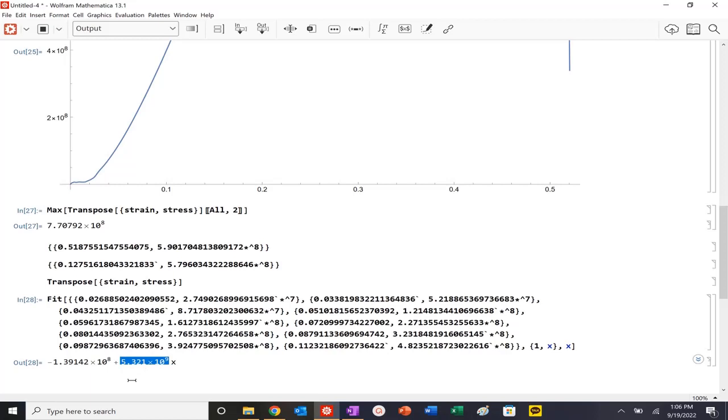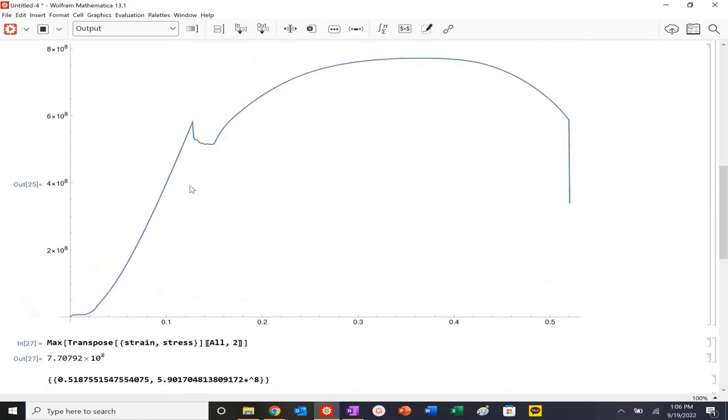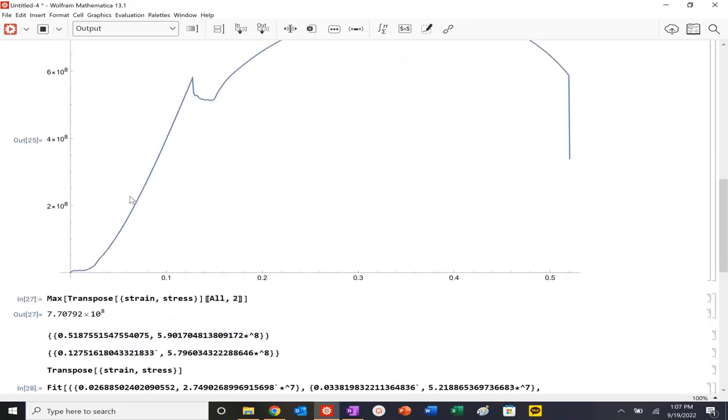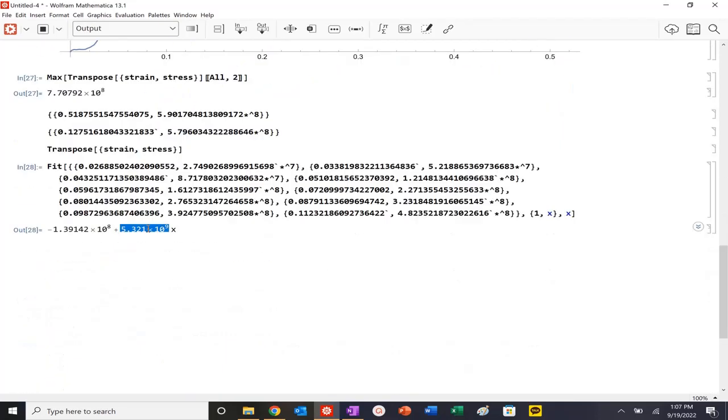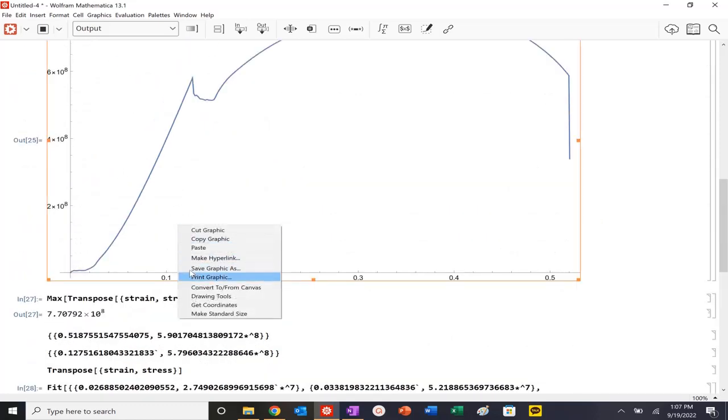So that is already telling me maybe it's some type of brittle polymer, maybe a composite material. I mean, we're not exactly sure. It's definitely not a metal. It's definitely not a ceramic. So I would say something like a brittle polymeric material. They can fail at relatively larger strains too.